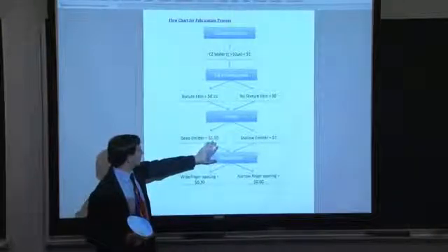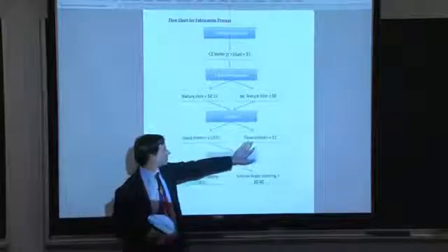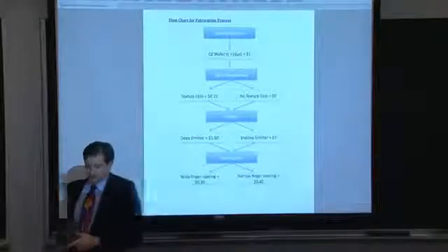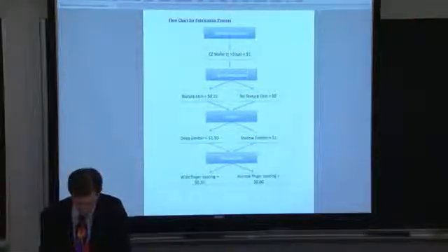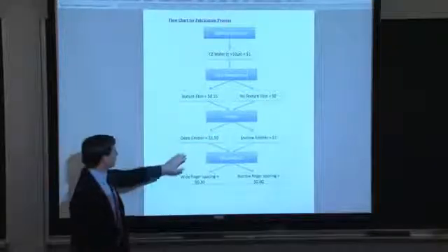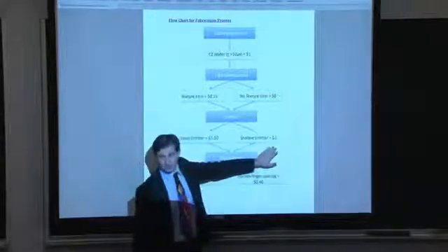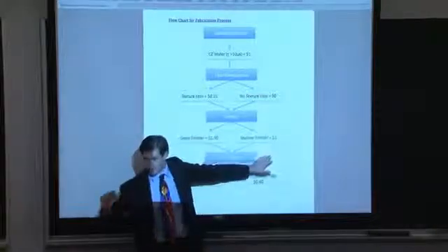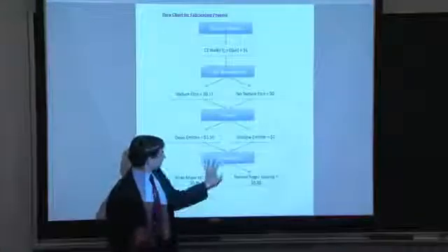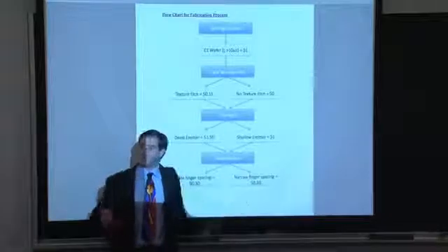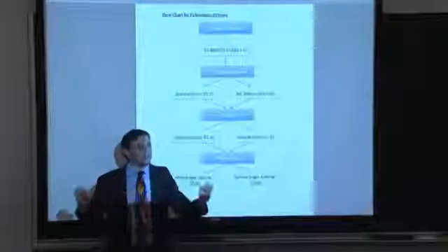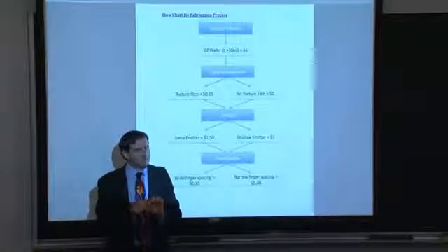Next on the emitter, the choice is whether to make a deep emitter or a shallow emitter. The text goes into that in some detail, but your decision is basically, if you make a shallow emitter, you have less Auger recombination in that front region, and so your blue response to the device will be better. But you run the risk, when you do your contact metallization, of firing through that very shallow emitter and shunting your device.